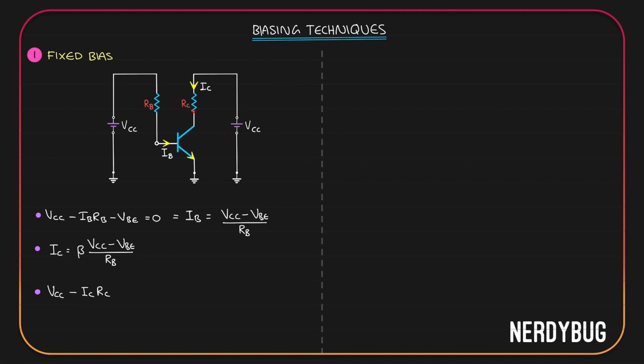As I further go on, I can see the collector and emitter. Whatever is the potential across the collector and emitter, I will call it VCE. It will also have positive here and negative here, so I will write minus VCE. These are all the potential drops in the loop, so the sum should be equal to 0.